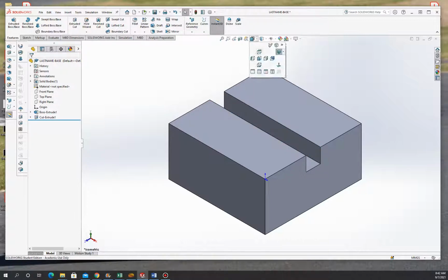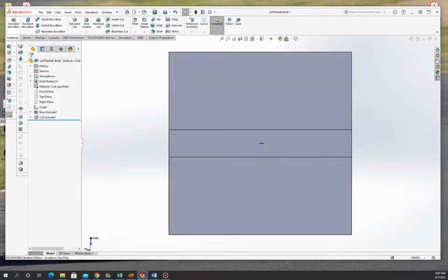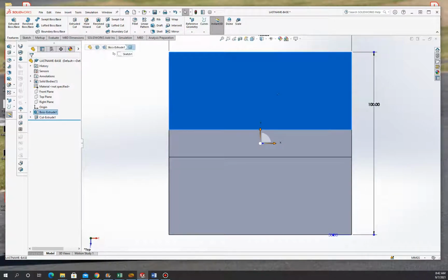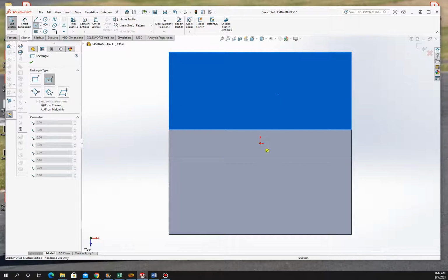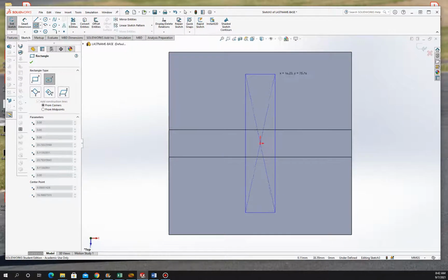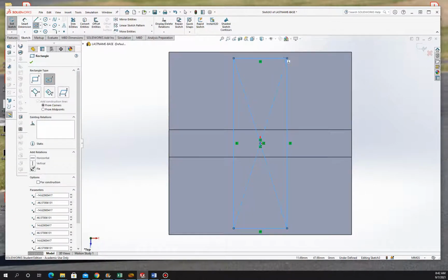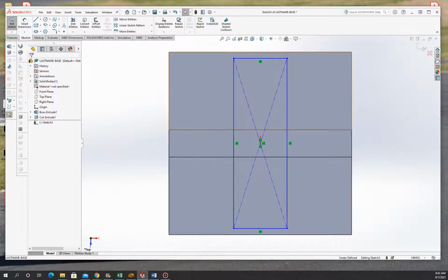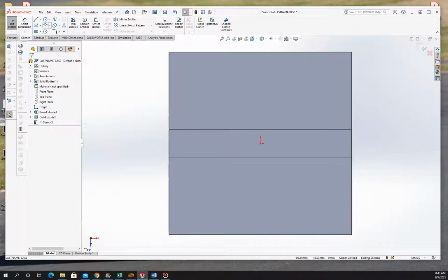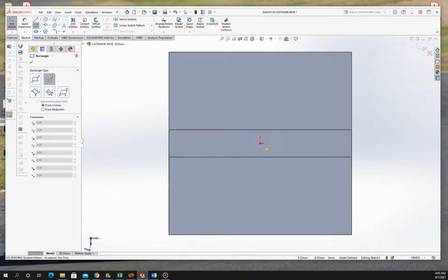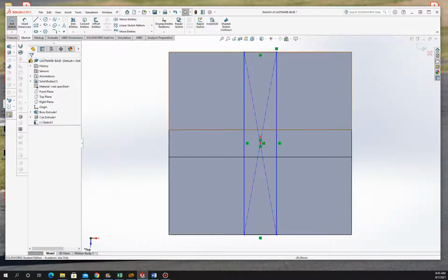Again, top view. Okay. Select that surface. Sketch, set a rectangle again. This time though we're going vertically, and again just get it so it's tangent to that edge, so you see it turned yellow. Oh, mistake. That's okay. I'll get rid of my mistake. Let's do that again. All right, and I drag it up, turns yellow. Escape once. I escaped too quickly just a second ago.